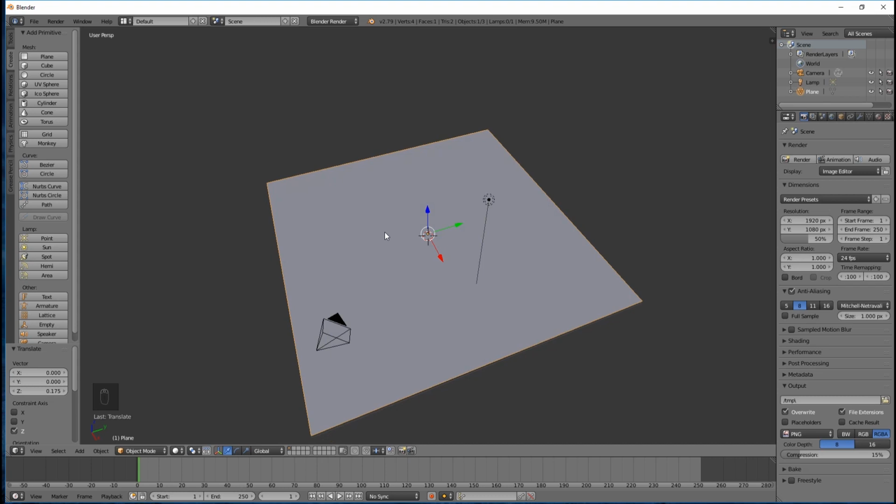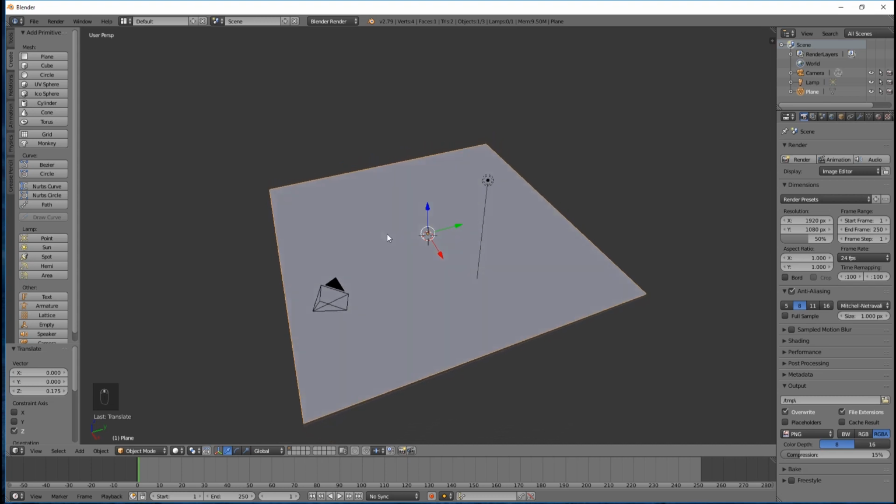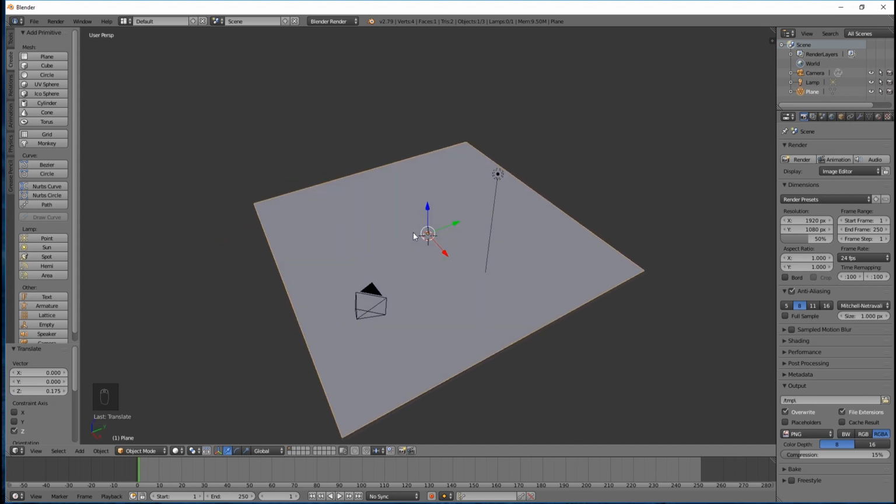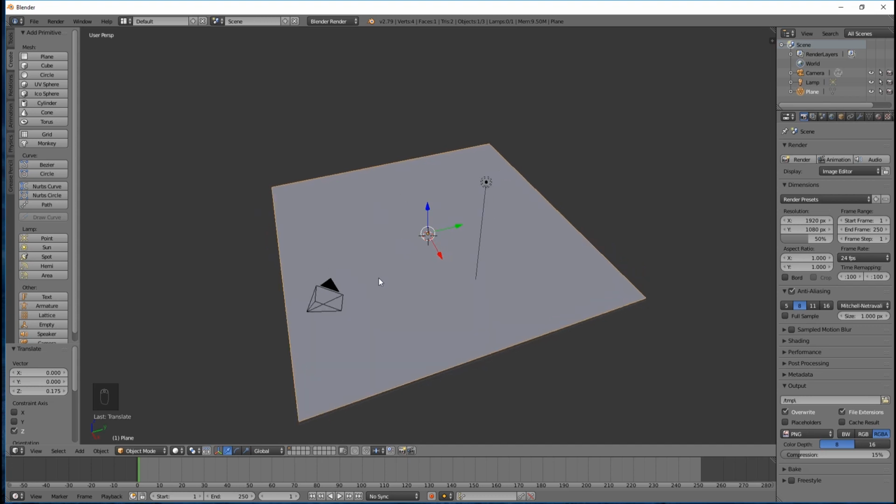Now what we have to do is sort of deform this, and there are two main modes of working in 3D software. One is with the physical models, the actual objects, the blocks, if you like Lego bricks, sticking them together. The other one is where you can take an individual object or Lego brick and twist it and stretch it and pull it and distort it in all sorts of different ways. And to create the rolling landscape of our island, that's what we need to do with this plane. So what I'm going to do, to begin with, is come down to the bottom left area here where we have a menu that currently says Object Mode. I'm going to click on that and switch over to Edit Mode.